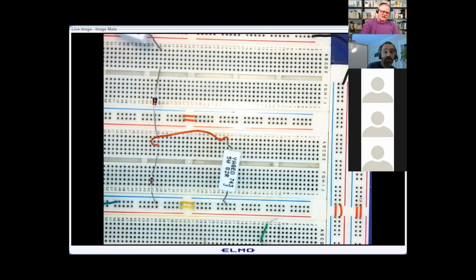Number one is Zener diodes are regulators, and they are going to lock in the voltage. Load resistors will change depending on your circuit itself, so they can vary up and down a little bit. So load resistors are not always the best, but they're practical when you want something quick and cheap and easy. We use them quite a bit in circuits where we're taking a reference voltage. But if we're trying to control something on another end, such as a microcontroller, and we need exactly 3.2 volts, Zener is where we want to go.